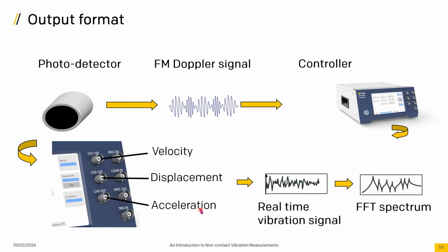So it's basically just a signal, a voltage in its purest form. It's just a voltage that is proportional to velocity or displacement. So that's one of the questions we get asked: what does it measure, velocity or displacement? And the answer is both. Both those are considered direct quantities, and then acceleration is the derived quantity when it comes to vibrometry.